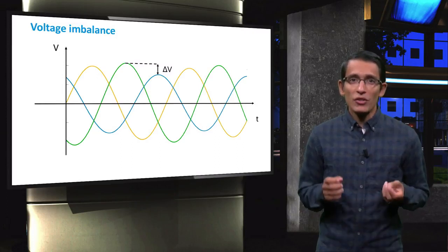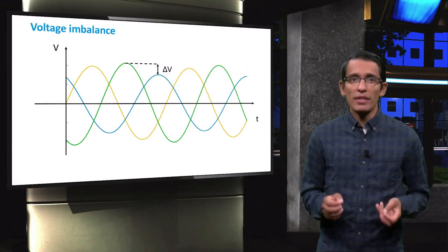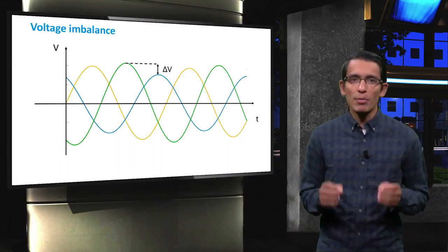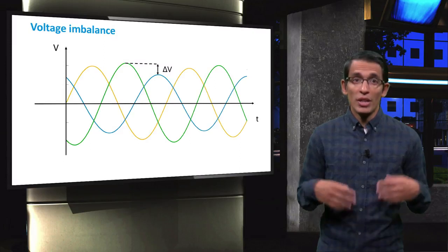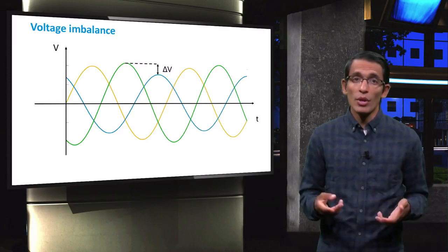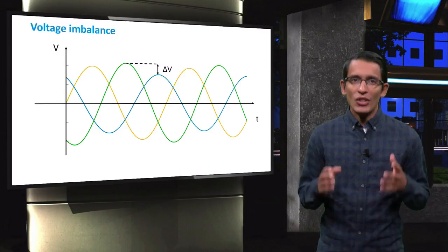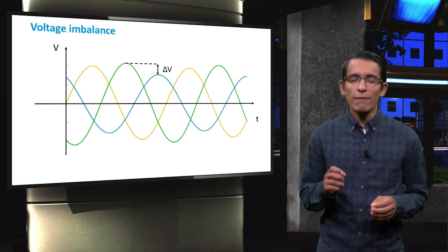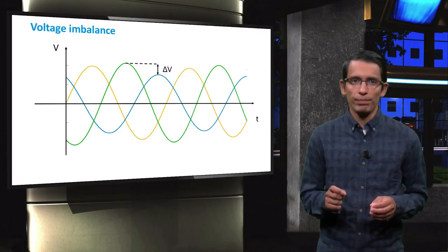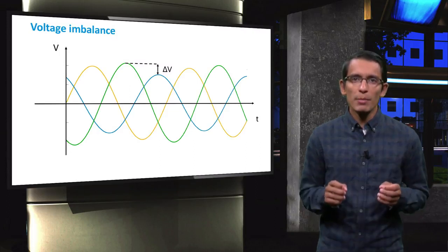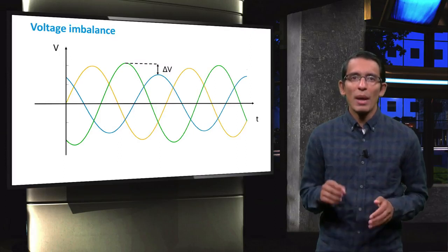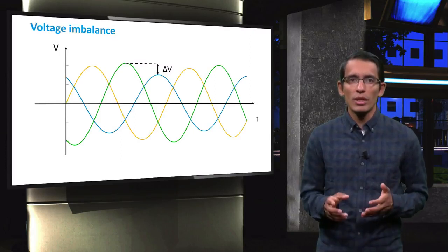So, if a single-phase generation gets distributed in the three-phase system, this can lead to an imbalance that will have a negative impact on small distributed generators, such as temperature rise of the rotors, noise, and vibration. Generally, the difference between the highest and the lowest voltage should not exceed 4% of the lowest voltage. Single-phase PV systems installed disproportionately on one of the three phases may cause severely unbalanced networks.